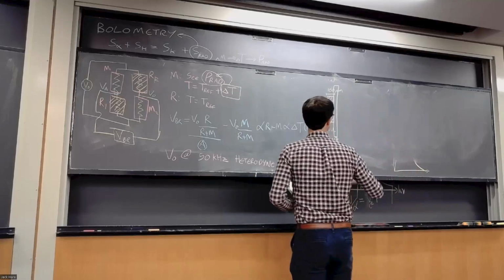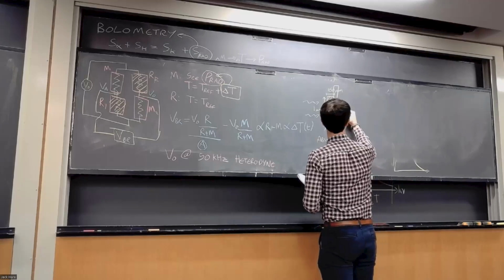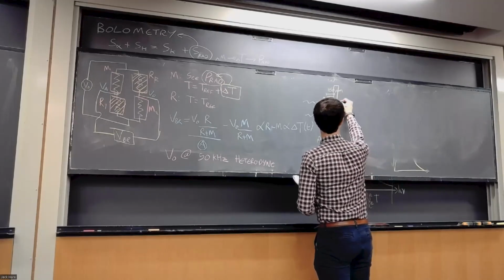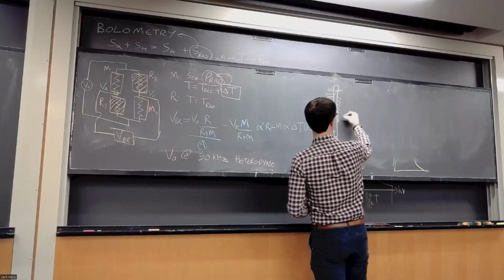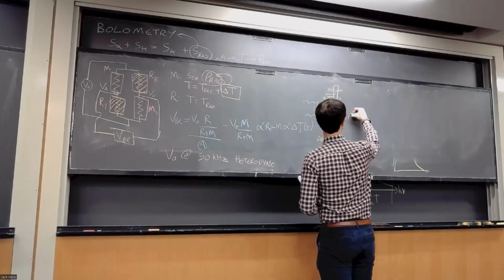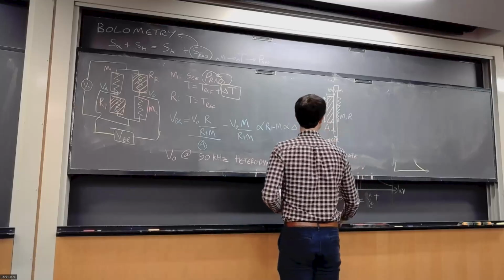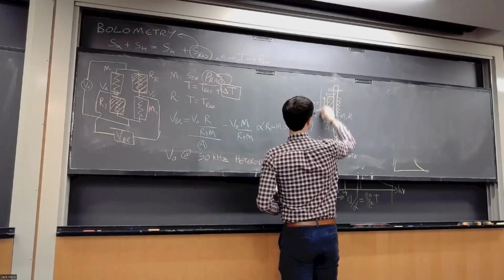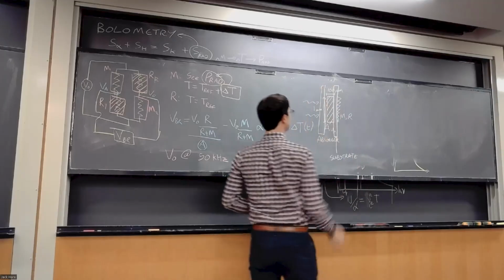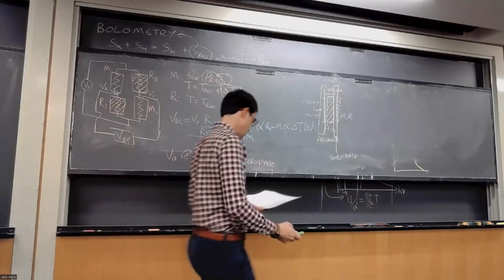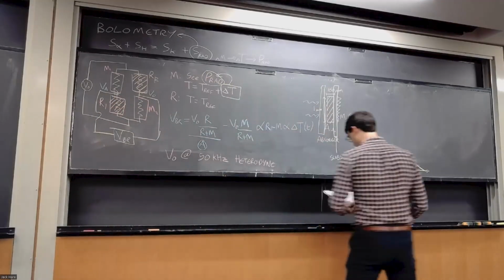And it's on the back of the substrate that you have your resistor. And your resistor is literally a little zigzag of gold deposited on the backside of this. So this is M or R. And depending on whether it is M or R, you either have this open to the plasma or you have a thick block some distance in front of it so it can't see the plasma.